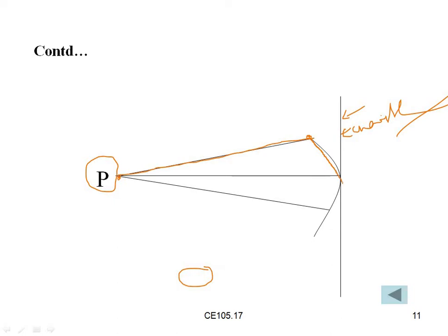It touches the chainage line and moves to this side. Whenever it touches, that point is the center of the point which is determined. This to and fro moving process is called swing offset.